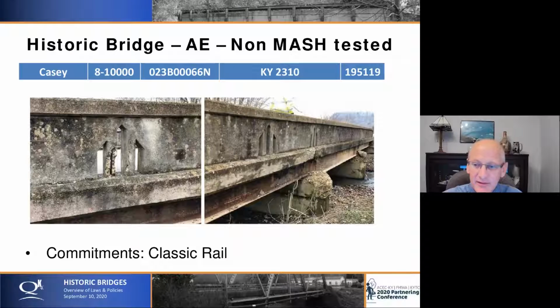And from the engineering and the safety side, you should raise your hand and say, hey, that's not MASH test certified, that's not safe. And that information should be on the table. But also part of the process is we may end up keeping that historic railing, and may have to have a design exception to preserve our historic resources for that context. So it's always context driven. And we run into that conversation all the time.